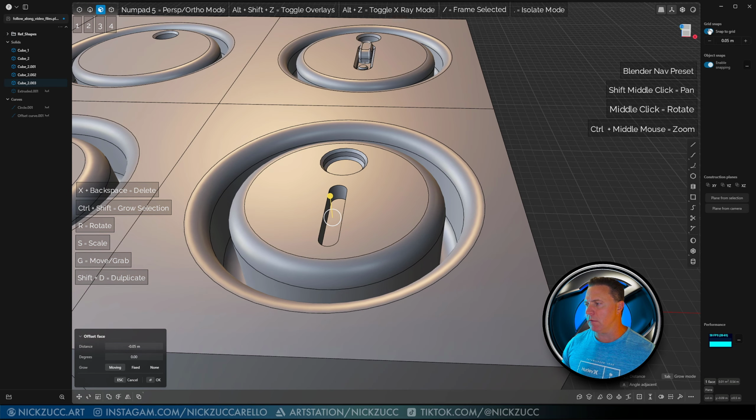I'm going to try to get a shape, and I need like half of this shape that we see here. So I'm going to take the line tool, and we can go to the center just like this, and I'll click here and here just like that, and looks like it's good. And now I can imprint that. So I'll do Shift I, select the body, hit Enter, and I can take that edge that we see here, and I can just tap H to hide it. And then now I've split that face, and now I can grab this and I can just push this up.